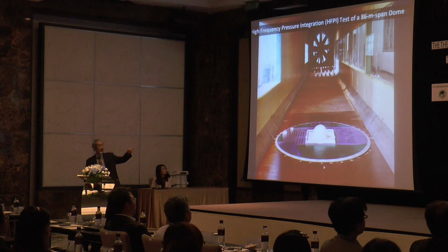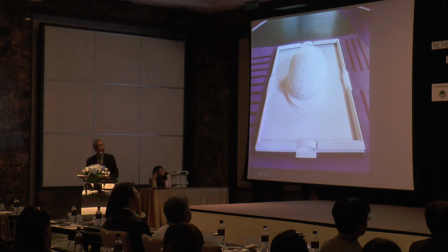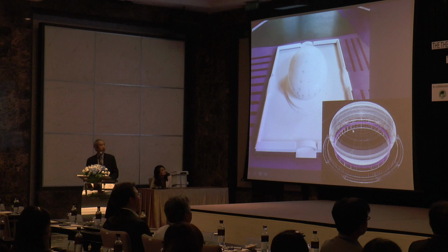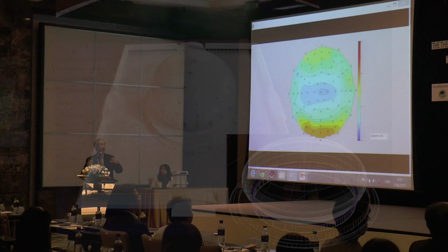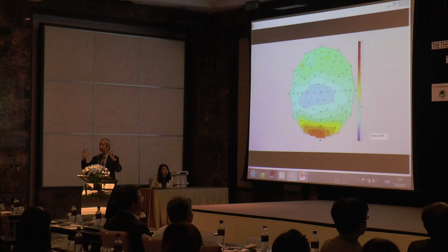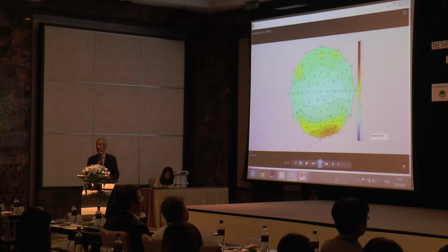The project here is about a dome structure. And this is the project we just finished about last month. It's a dome system. It looks like this. And to design this dome structure, which is a very light, long-span dome, you need to know the wind pressure information. This is how it looks. We measure pressure at different locations on the surface of the dome. We measure all this pressure, all of them at the same time. And this is the wind direction coming from this side.